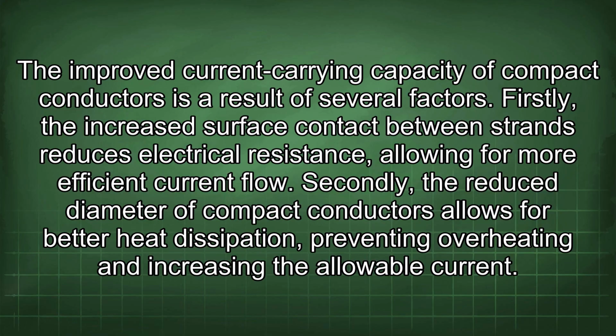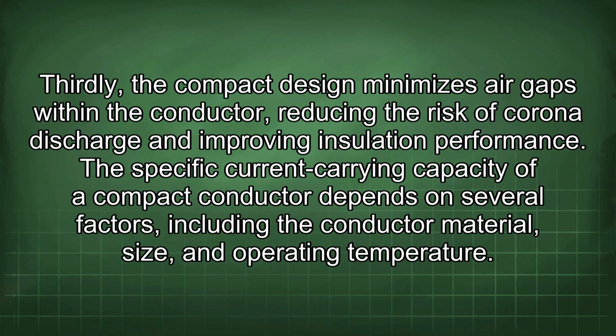Firstly, the increased surface contact between strands reduces electrical resistance, allowing for more efficient current flow. Secondly, the reduced diameter of compact conductors allows for better heat dissipation, preventing overheating and increasing the allowable current. Thirdly, the compact design minimizes air gaps within the conductor, reducing the risk of corona discharge and improving insulation performance.